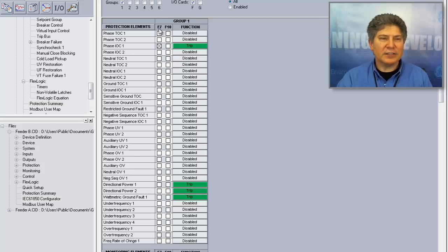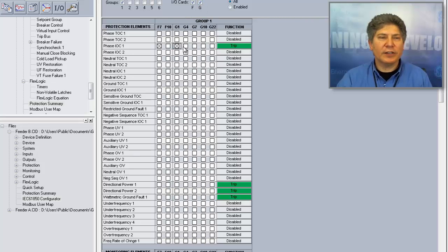So this is an F. So this is output relay aux 3. F10 is aux 4. If I was to bring up the G's, then these are the additional output relays. So those are the slots, the physical position where these are. Correct. This is the physical terminal connection on the back of the relay for the relays. Okay, so which is in addition to the trip. In addition to the trip, that's correct. Okay.